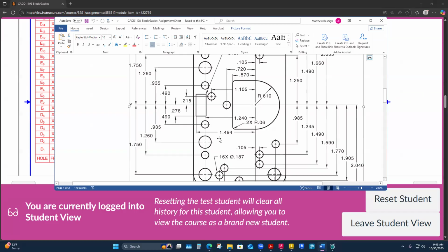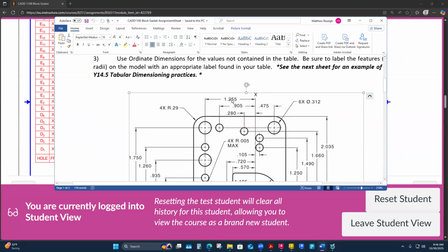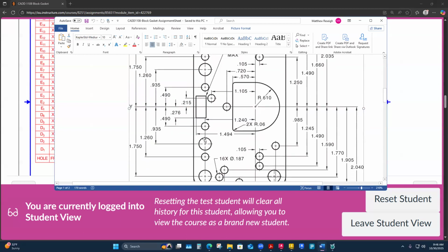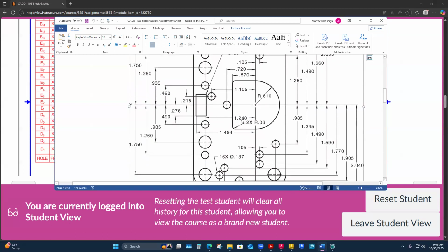But I think when I really analyze this, and maybe back check another faculty's prints, maybe, I think that these were all on the same center line as these across, and that 1.24 is a misleading arrowhead. I think it should have shown that it's right here, but it's hard to say. Clearly there's a difference here, and the only missing dimension I had was this one, even though it's really not missing, it just seems misaligned.